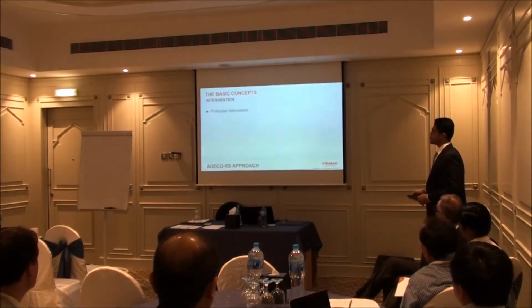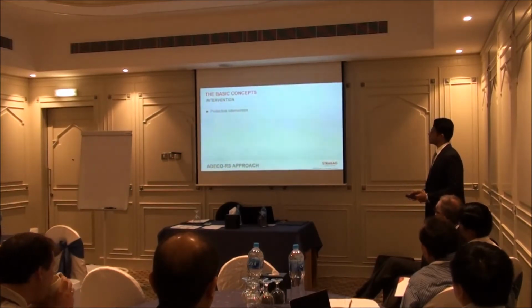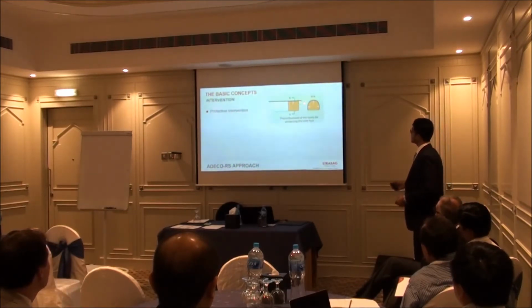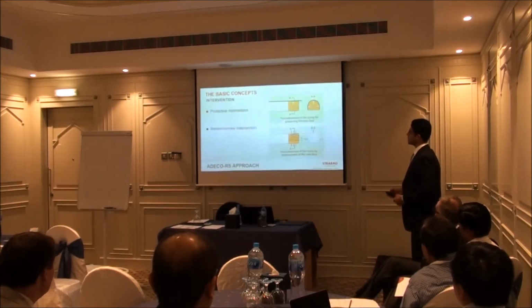So what type of interventions can be done? One type is protective intervention. Protective intervention is done ahead of the tunnel core and only to protect the tunnel advanced core. The reinforcement intervention is done to reinforce the rock, the advanced core itself.